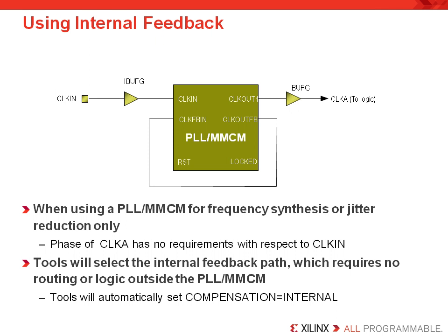The PLLs and the DCMs in Xilinx devices have multiple clock outputs. Multiple clock signals that are generated by a single PLL or DCM have a known phase relationship. And since the delay through all global clock buffers and global clock networks is identical, these clock signals will maintain their phase relationships from the clock source all the way to their loads.